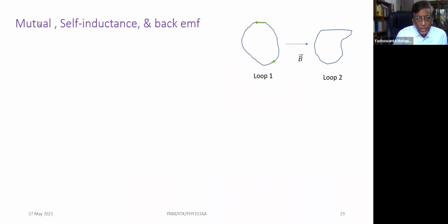So we have seen mutual inductance, but that could be any circuit. It need not be two loops, though of course here we have loop 1 and loop 2. We have seen that the EMF depends on minus d phi by dt, and that should be minus mutual inductance times di by dt. This is how we use the rate of change of current in our transformers, where the two loops are connected through the mutual inductance.